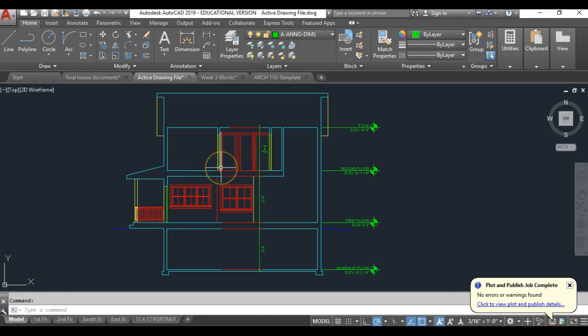Now the first thing that you need to do when you're figuring out stairs is to figure out how many stairs or how many risers you actually have. And you have a hint already on this because we've already figured it out and we've given it to you in plan and you can count them in plan. And it turns out that you have 8 on each side for a total of 16. And you can go with that, but I feel like in this video I should tell you why it's 16 in the first place.